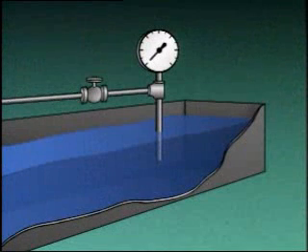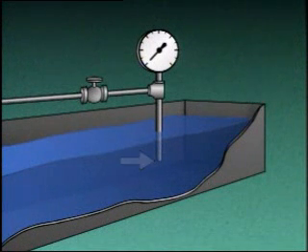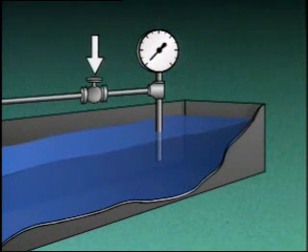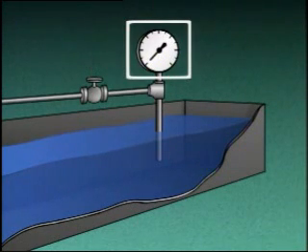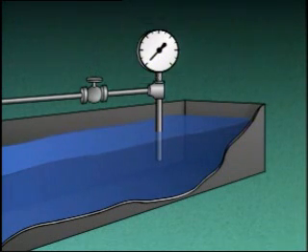An indirect liquid level measurement device called a bubbler system uses hydrostatic pressure in a slightly different way. It operates by forcing air out of a pipe that's immersed in liquid. The system consists of a pipe that's open at the bottom and connected at the top to a regulated air supply. There's also a pressure-sensitive gauge, which is used to indicate level.